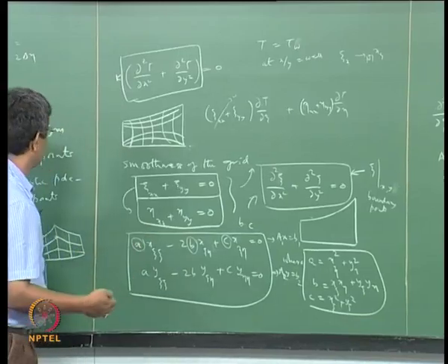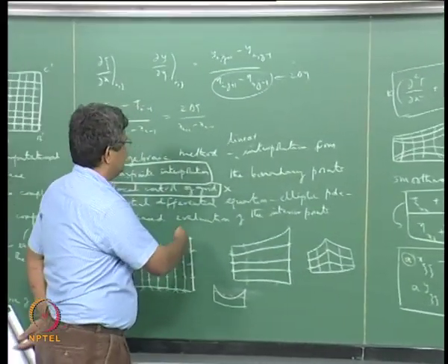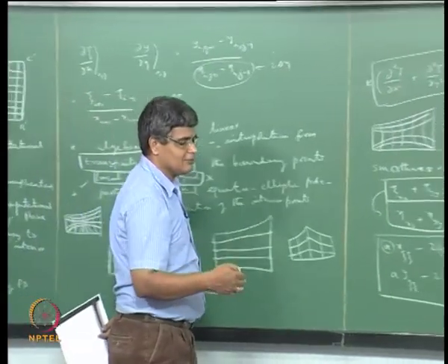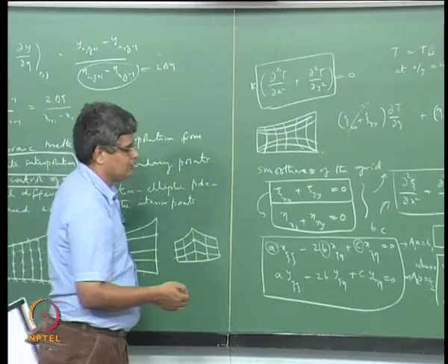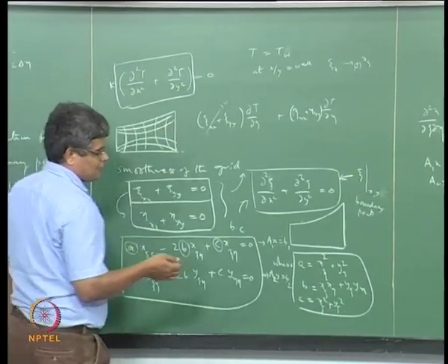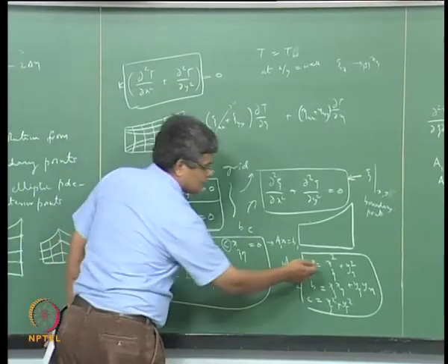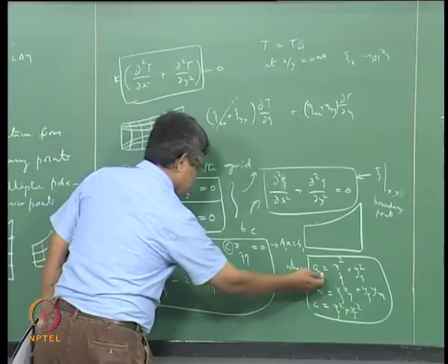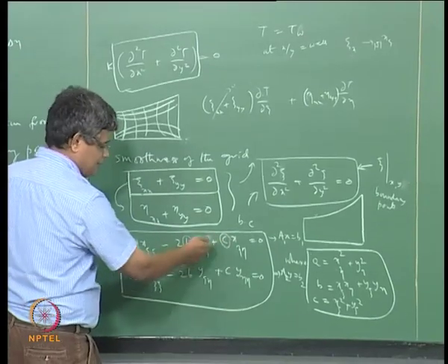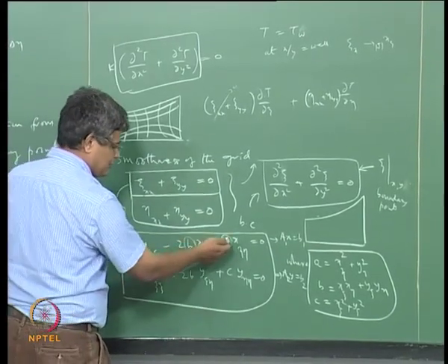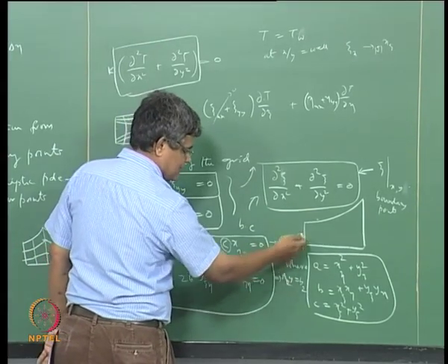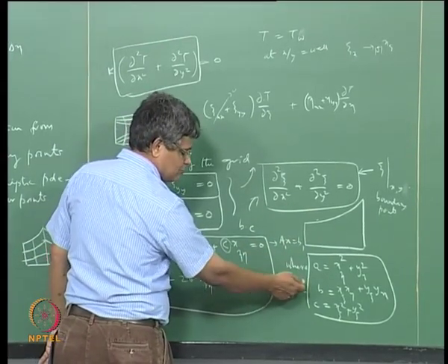So we can start with a linear interpolation or transfinite interpolation to get some rough known values for the interior points, use that interior point information to calculate the metrics here, and then put them into this. Now we have a partial differential equation with known coefficients. This we convert into a1x equal to b1 and also this into a2y equal to b2.